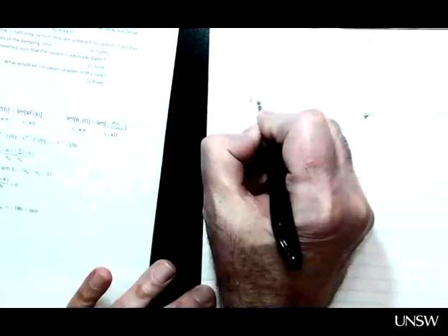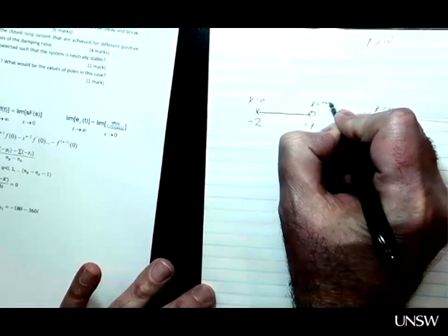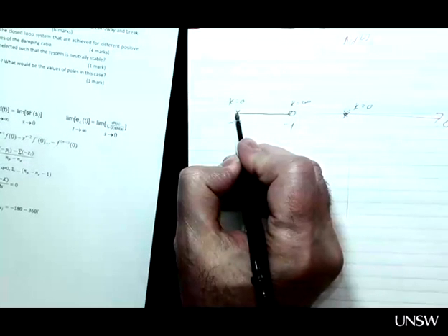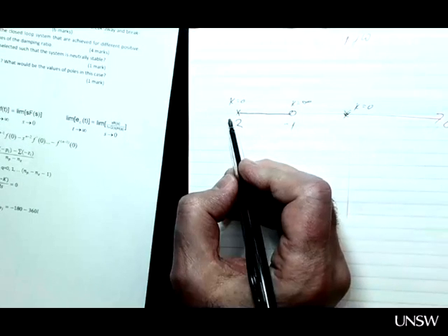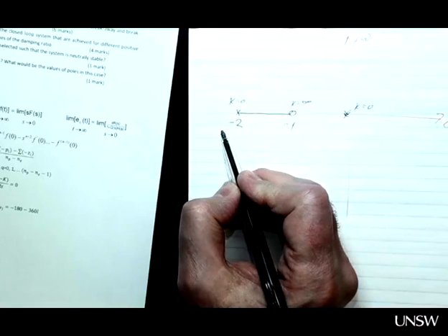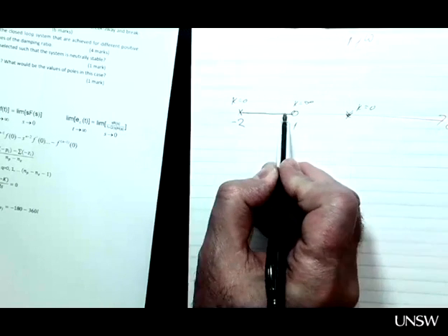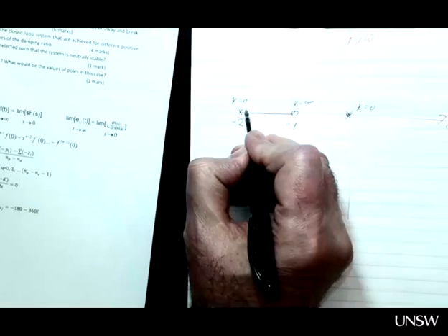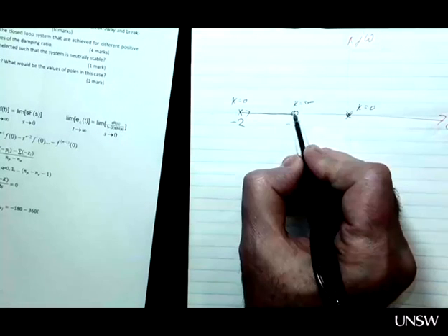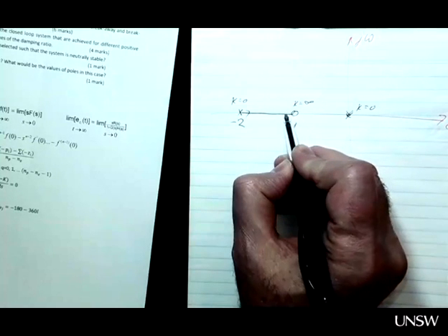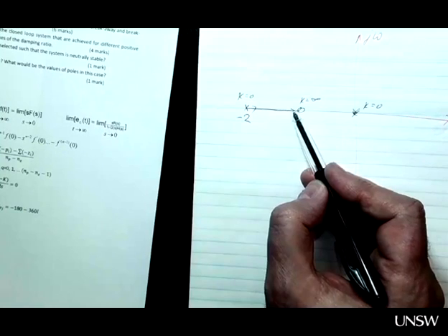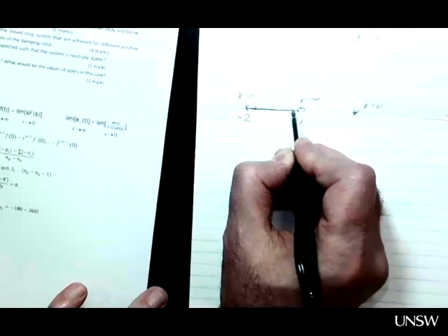Okay, so now there are a few things we know. This is where k equals 0. This is also where k equals 0. This is where k equals infinity. So the root locus starts here at -2 and moves as k increases from 0 to small positive numbers, then bigger and bigger. Where does this pole move? To the right. It has nowhere else to go but to the right, because this segment, once we determine this segment, we know that. On the other hand, this is where k equals infinity, so this is where the root locus finishes. It has nowhere else to come from apart from the left. So you can safely say that this pole will move towards this 0 as k becomes bigger and bigger.